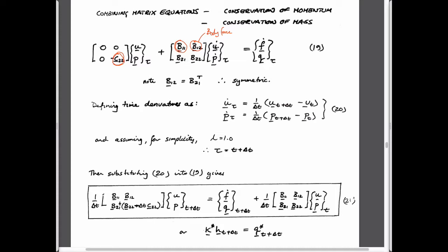This term here operates on displacements. So this is the fluid out due to strain. And if you like, this is fluid in due to delta V fluid, due to delta P, changing pressure. So you change the pressure in the fluid, you change the volume in the fluid, you have to make up that volume from the surrounding elements to be able to keep continuity. So those are the individual components.